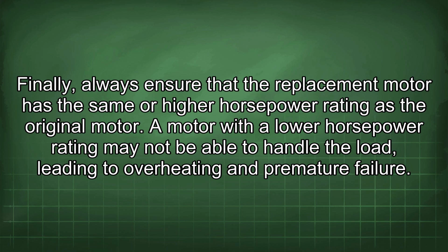Finally, always ensure that the replacement motor has the same or higher horsepower rating as the original motor. A motor with a lower horsepower rating may not be able to handle the load, leading to overheating and premature failure.